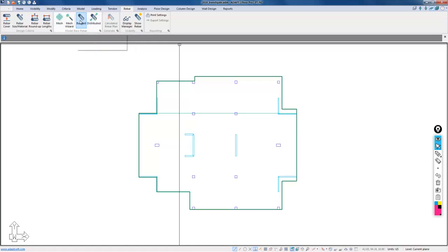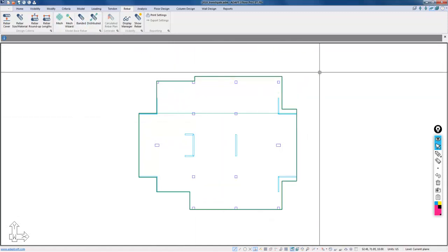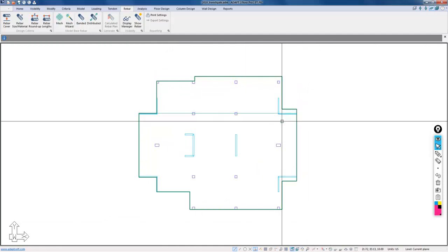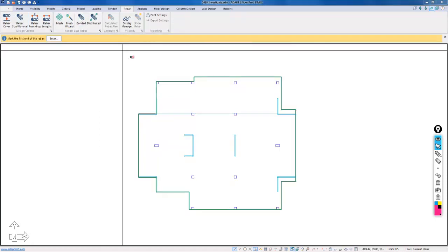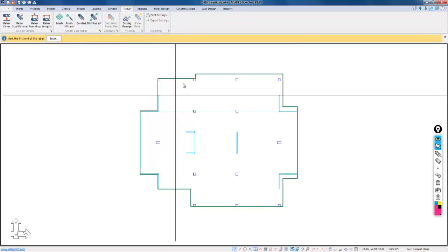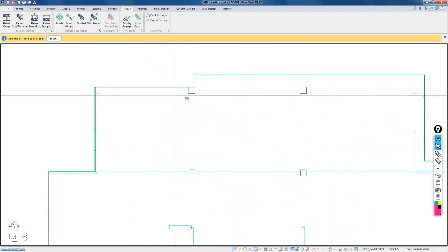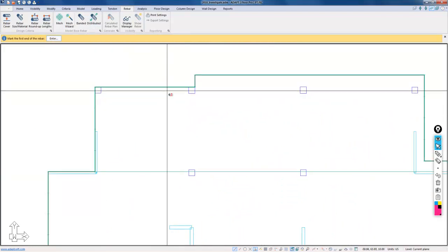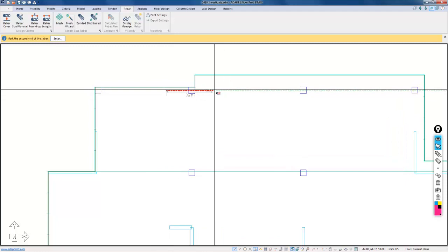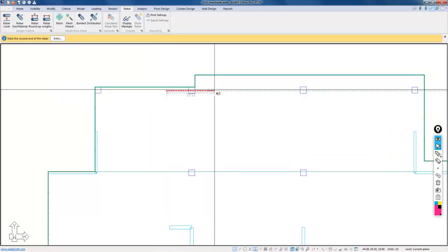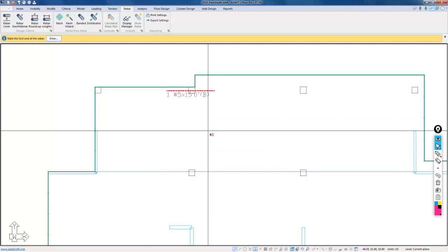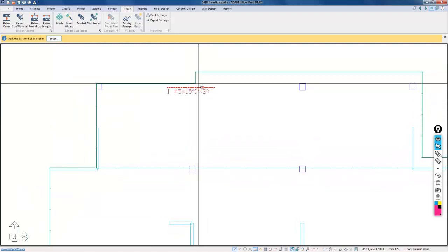We're going to start with adding banded reinforcement over these columns here and the end of this wall. And we're going to just use some arbitrary selections for the banded rebar. So I'll first start by just selecting banded, and I will go ahead and just draw in a piece of banded rebar. You can see once I click a point, the dynamic dimensioning will show me the length. We'll just assume it's 15 feet here.